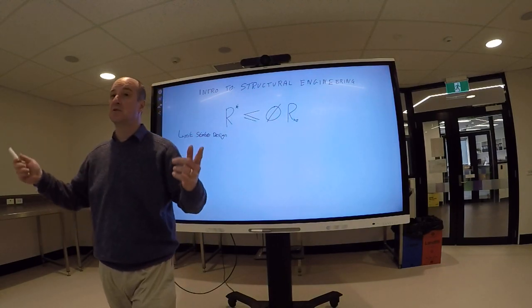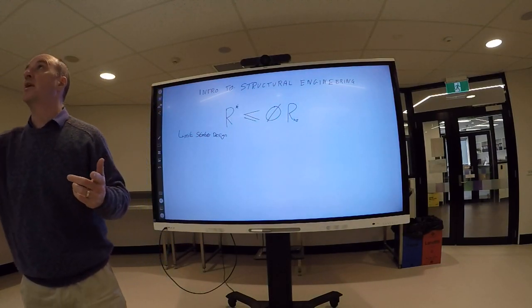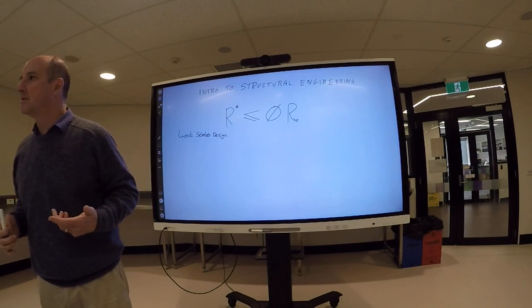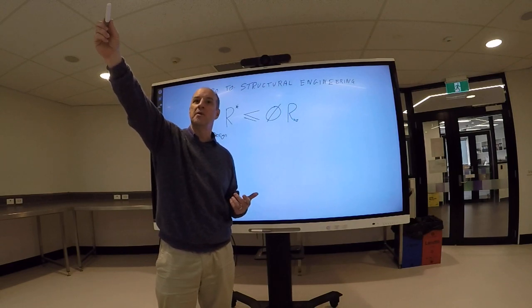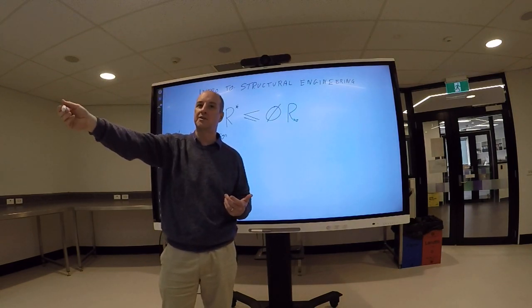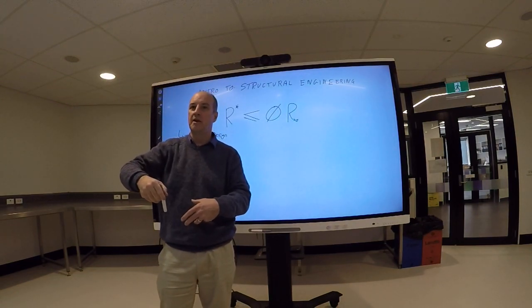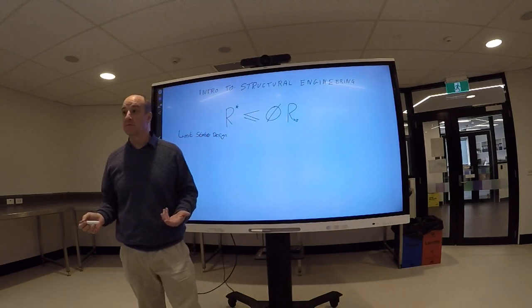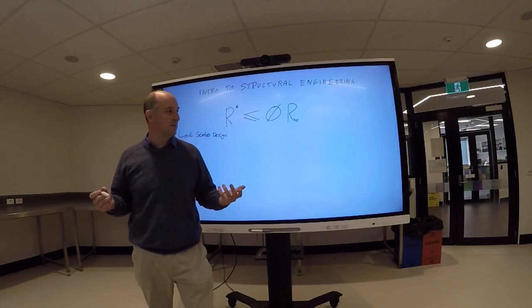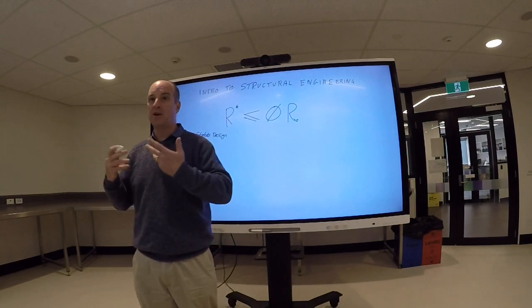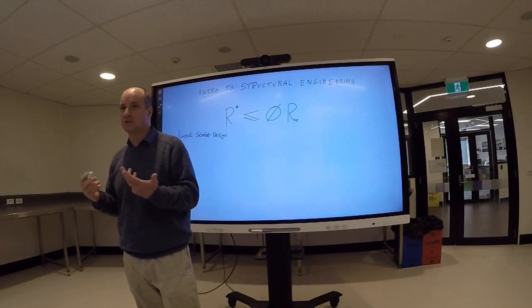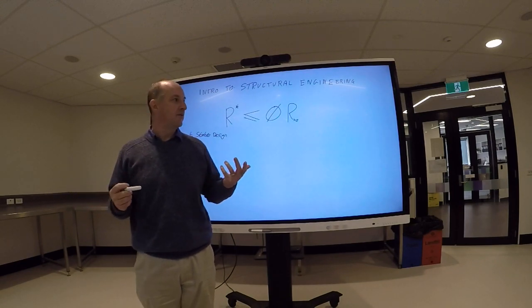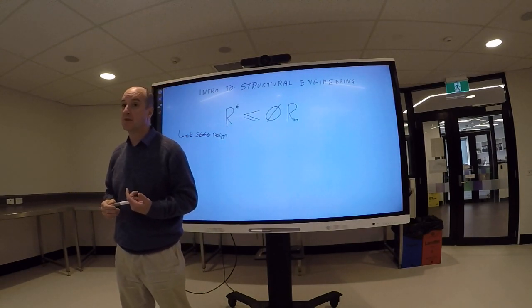If we take this building, for example, the strength is about whether this thing's going to collapse or not. That's easy. The serviceability is if that beam bent so much that the snow actually sat on the roof and didn't drain off and the water came in the building, that would be a serviceability failure. If something moves so much that the doors jam and the windows break, even if it's strong enough that it's going to support the house, that's a serviceability failure, okay?